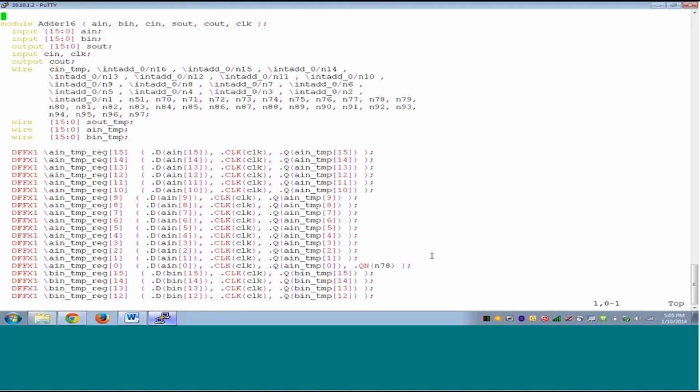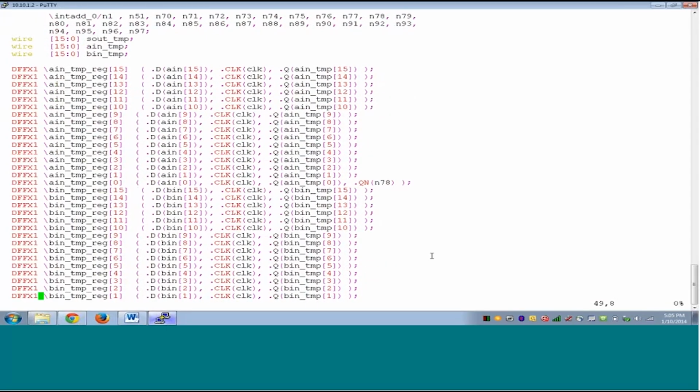Now, if you notice, there are backslashes in the names of wires, and probably this wire was 16-bit wide, and it is split like this: backslash, the wire name, and slash, and N16 enter, and so on. We see that the instance names have backslashes and so on. This is the way Design Compiler operates when it works on a design, and when we write out Verilog, it will write out in the same format. But this netlist will have problems when some third-party tools read it.